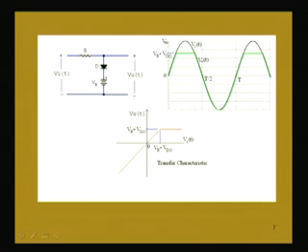That is shown here by this red line; this portion is for the non-conducting portion of the diode. From this point onwards the diode is conducting, and the voltage drop is constant at this voltage Vb plus Vd naught. So, this portion is the non-conducting portion where input and output voltage are the same, defined by this straight line passing through the origin having slope 1. This is an important characteristic which we can draw from the input and output voltage waveforms.